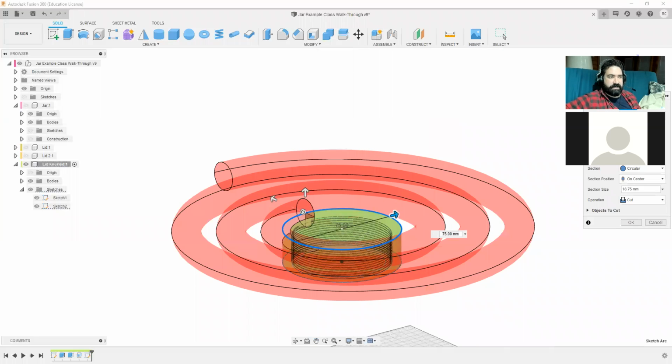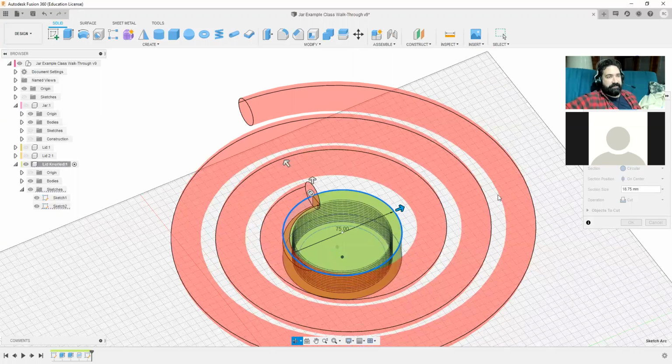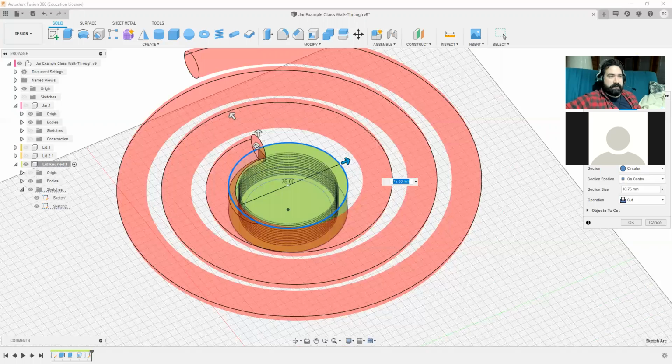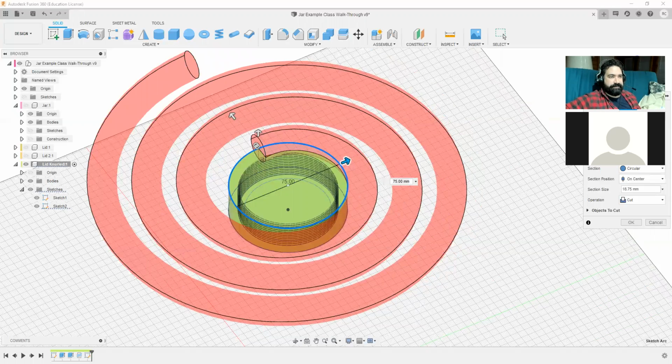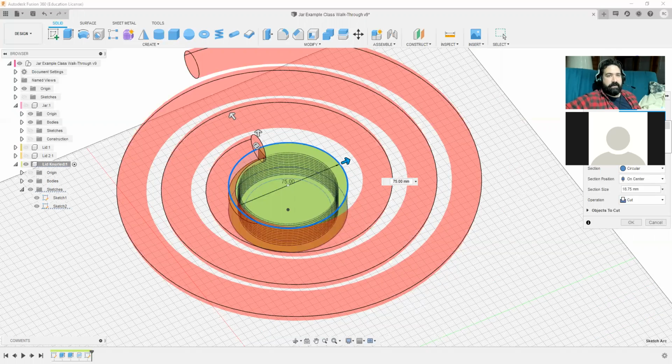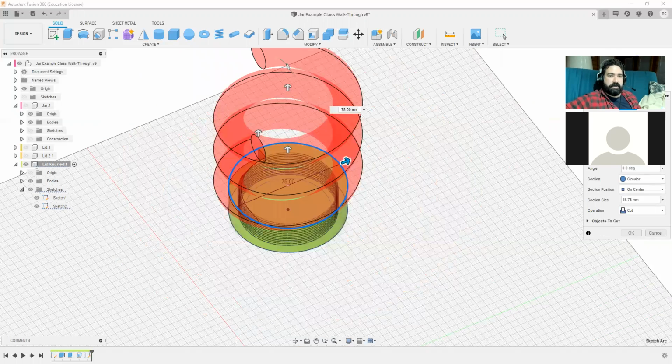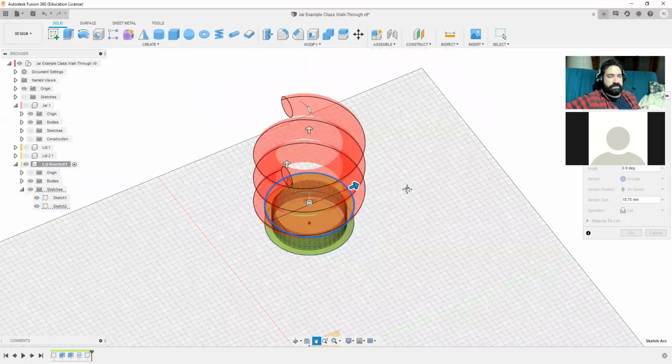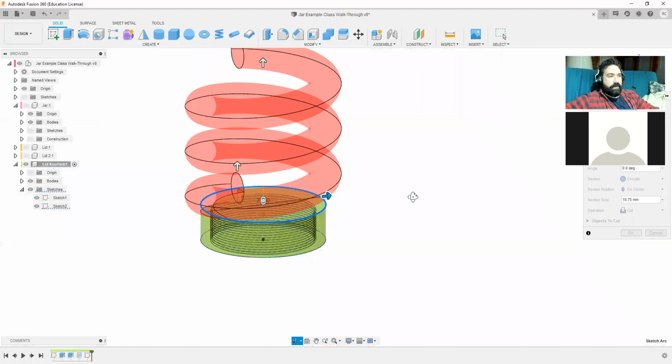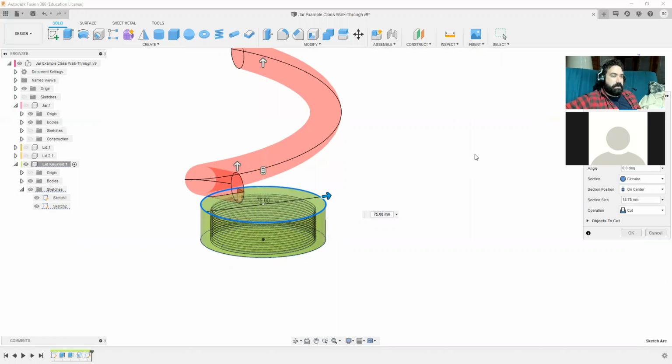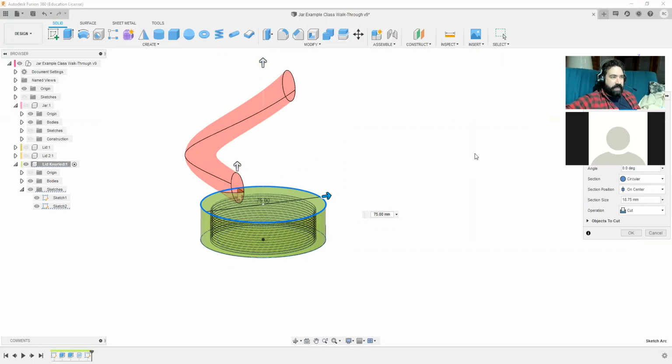I can do spiral. There's a flat, this is a new option. For some reason, it was not before, creating a spiral. You can always use the flip rotation, but I don't want a flat spiral. I want height and pitch. That works fine if you're trying to make threads, but just the default revolution and pitch works perfectly fine. Now, what I actually want, though, is for one revolution is even too much. So I'm actually only wanting half of a revolution. That might be too much even.